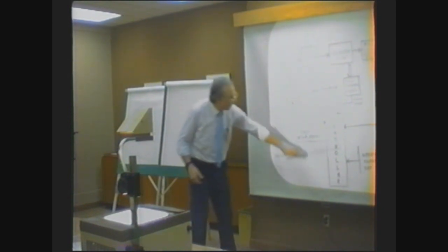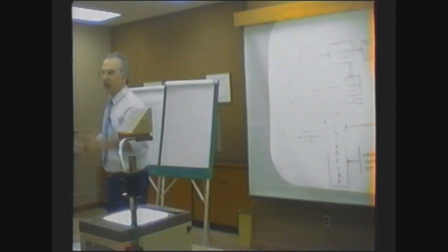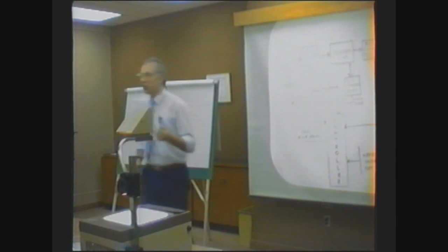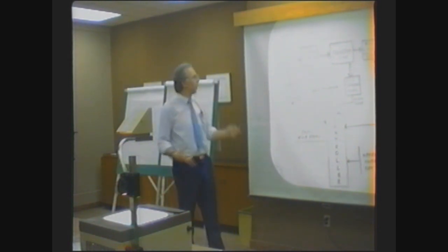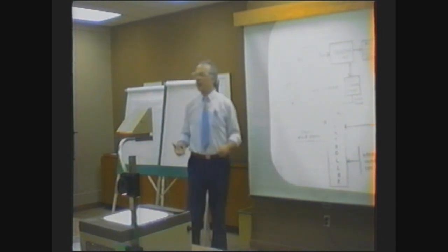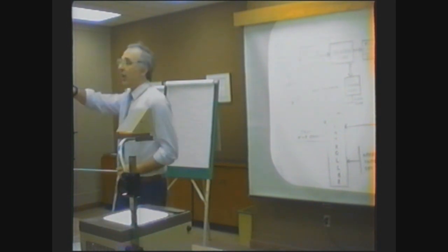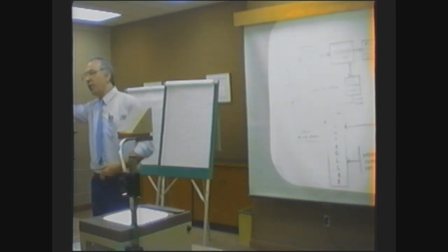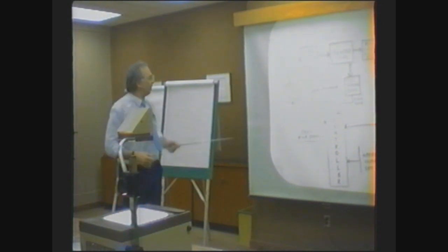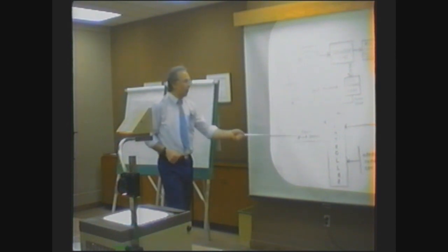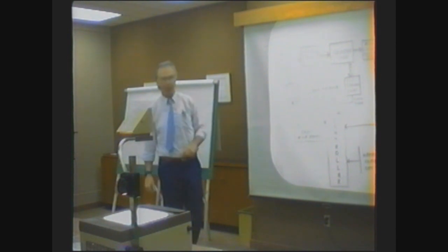And now the algorithm, which I'm going to explain shortly, marries these different inputs with some other conditions, and what comes out is the number of steps to the control mechanism depending on the input variables. In order to maintain the reactor power at a certain level, we have to pull out the rods, push in the rods, or leave the rods at the position they are. So what is going to come out is a number of steps, positive or negative, which means up or down, an increase or decrease in the power.